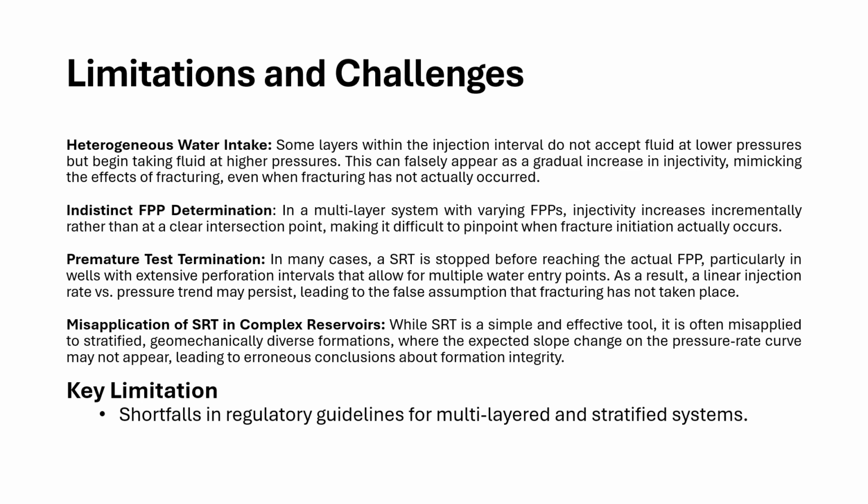So going on, another challenge that you'll find is the indistinct fracture parting pressure determination. In multiple layer systems with long perforated intervals, there are varying fracture parting pressures. And as injectivity increases incrementally, there is not a clear intersection point. More of a curve develops, making it difficult to pinpoint where the fracture initiation actually began.